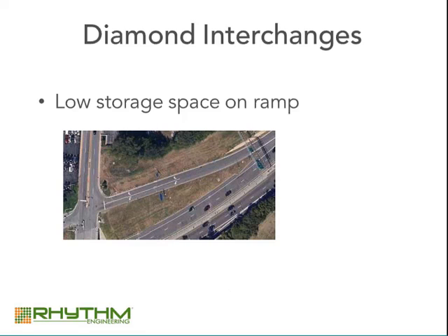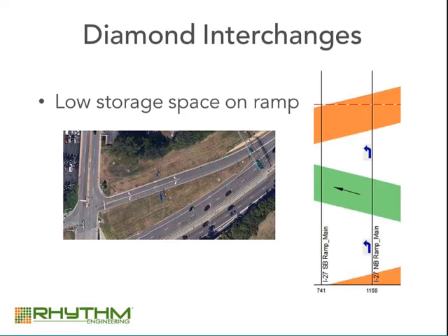Heavy off-ramp traffic may lead to other issues, such as the ramp itself not being long enough to store the queue without spilling back onto the freeway. In this situation, it is best to configure the InSync tunnels such that two side street gaps occur within one period. If you look at the Central Sync tunnel configuration, there are two opportunities to serve the ramp within one period. Doubling the frequency of serving the ramp will reduce the queue lengths and help eliminate spillback onto the freeway.